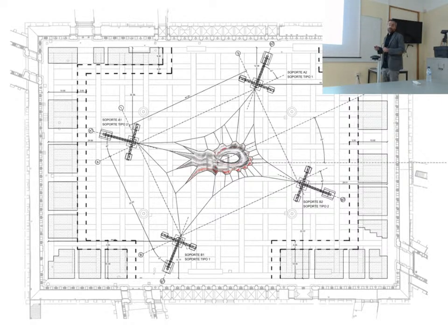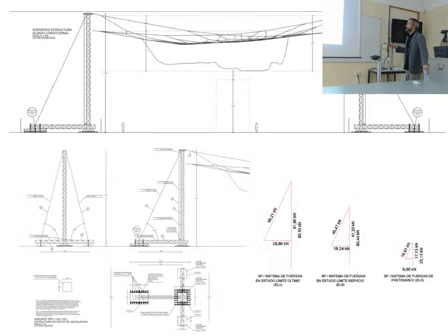And this is the kind of structure we were thinking of. First, we designed a proper steel structure, but we were advised that the budget was really low, and they suggested that, since the piece was meant to be there for 2 months, we try to reuse existing structures, like rental structures, to make it cheaper. So we said, okay, no problem. In the end, we used trusses for concert stages, dead weights from cranes, and auxiliary elements of the construction industry. So the structure is not very sexy, if you want, but it's cheap, and I think it's okay for being there for 2 months.